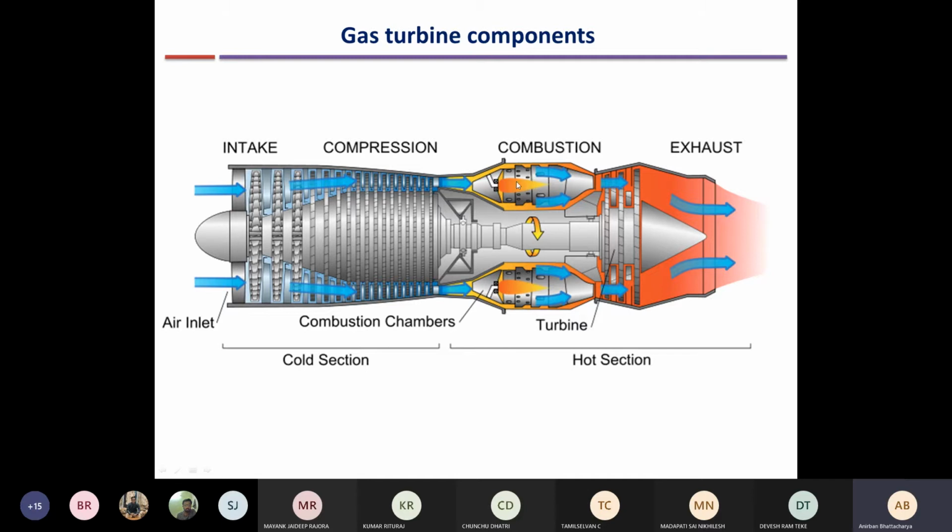This also has the added advantage that if the air fuel ratio is high, there is more chance of proper combustion, since more air is available, and almost the entire fuel gets combusted properly. As a result, the combustion efficiency here is much higher as compared to IC engines. It can be around 99%, meaning around 99% of the energy held by the fuel can be extracted as thermal energy.